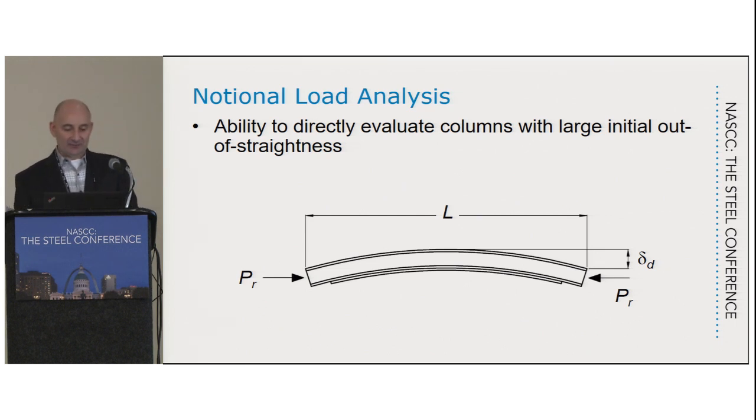And I briefly said something about this earlier too. The weld shrinkage distortion can cause the column potentially to have a larger out of straightness than what is allowed in the AISC Code of Standard Practice. And typically, if you're welding on both sides, I just rely on the welders to stagger the welds, and I'm not sure how they do it. It's kind of an art. The guys in the shop or the field would know a lot more about it. And there's information in Blodgett's book and several other references on this too, if you want to look into it.